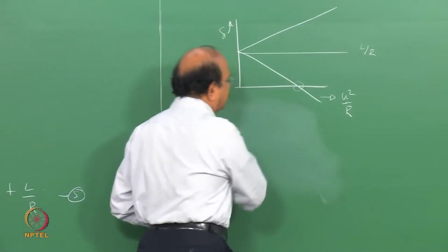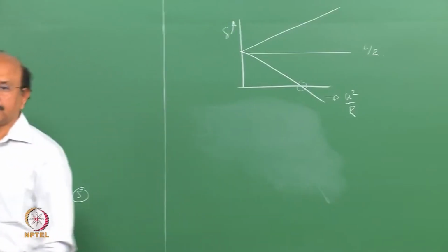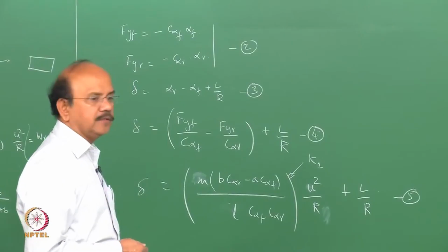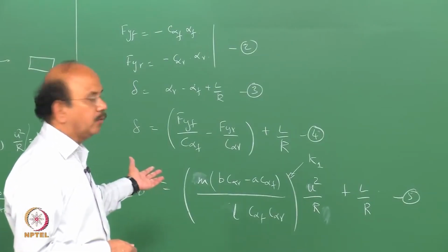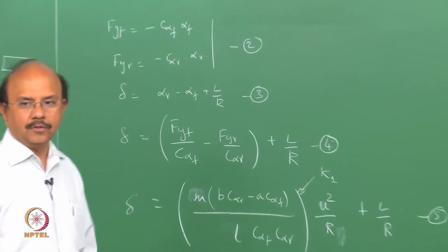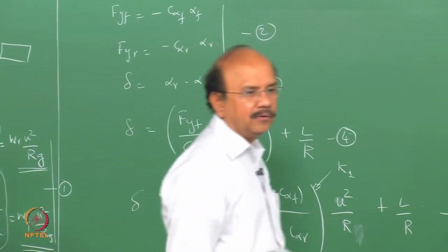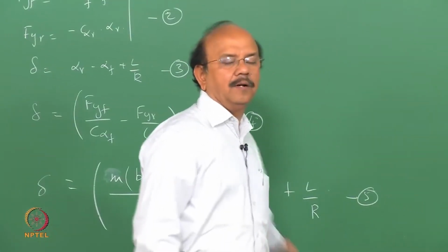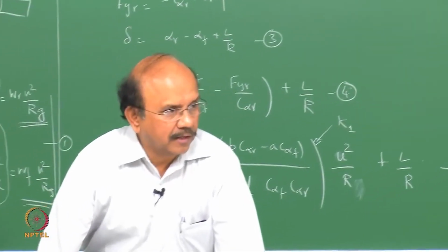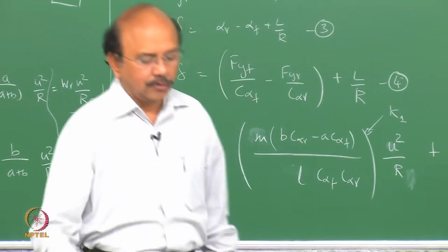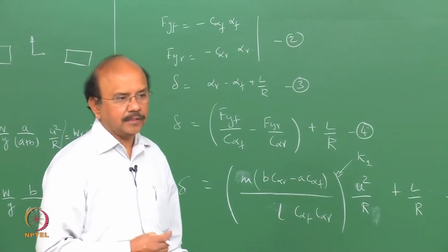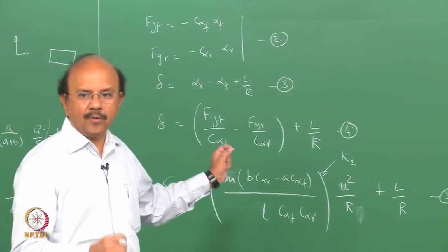Right. So that's the key factor on understeer gradient. As I said, the way it is defined is different. You can define this in terms of W and G out and so on. So be careful when someone tells you a value. We'll do some problems later. You have to be careful and ask what exactly is your definition. I have got into trouble like that before. So you have to clearly know how someone defines the understeer gradient. What is the formula he is using?